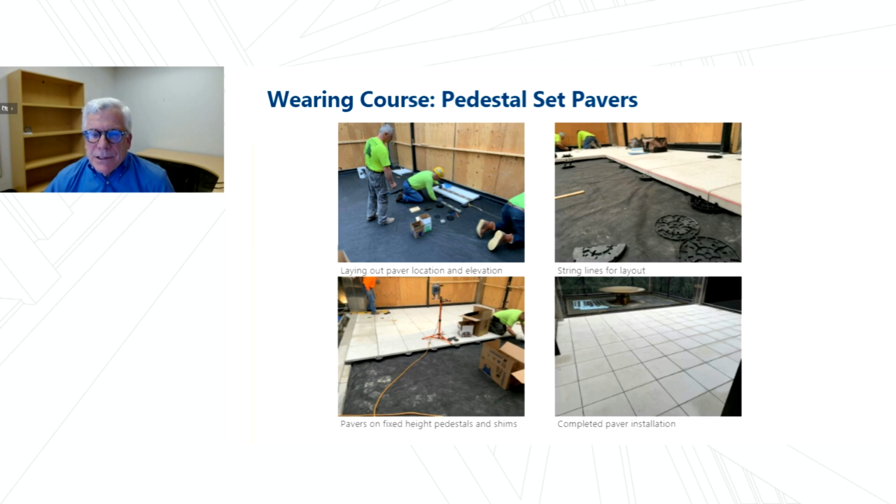With the pedestal system, this is the installation: laying out the paver locations, and then placing the pedestals, installing the pedestals, and then you can see the completed system. Once again, these can be installed in basically a flat horizontal condition where the water passes through, but they usually need a little bit of adjustment from time to time.